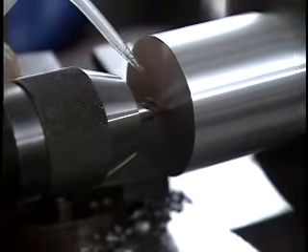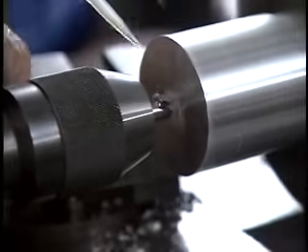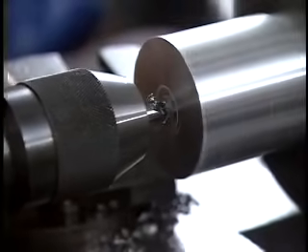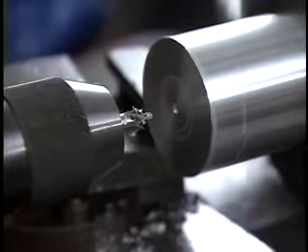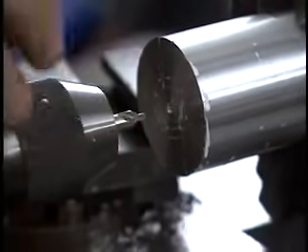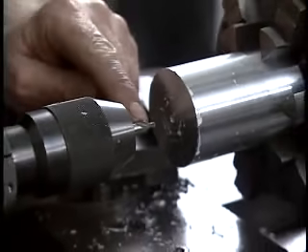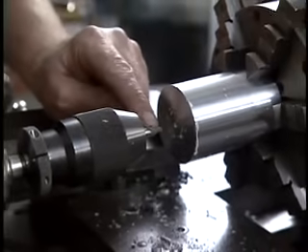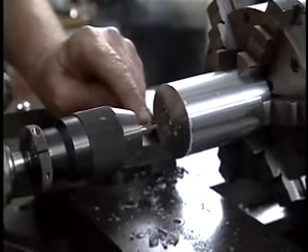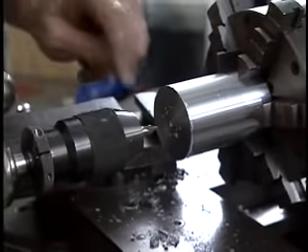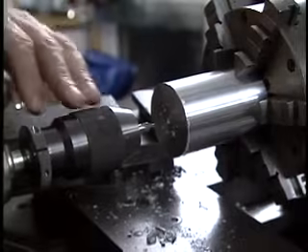When using a center drill, it's almost always a good idea to use a little bit of cutting fluid. This drill doesn't cut as well as a regular drill because it's a compromise between cutting like a regular drill and being very stiff. The result is that the chips that it produces don't clear out of the drill as well because these flutes aren't as deep, nor do they have as much of a twist as a regular drill.